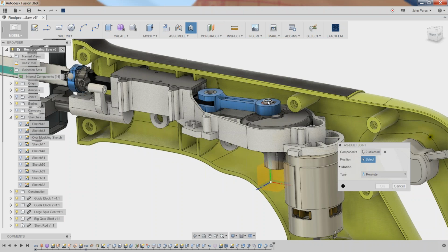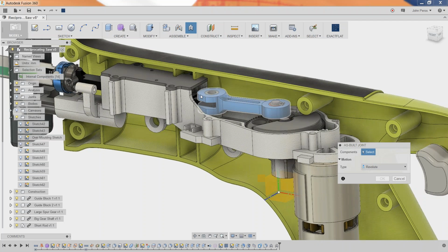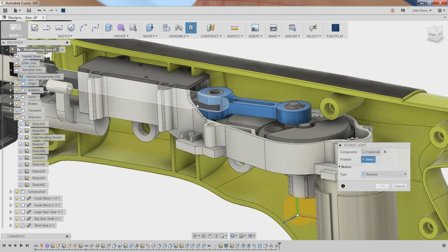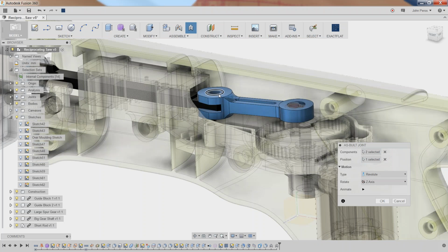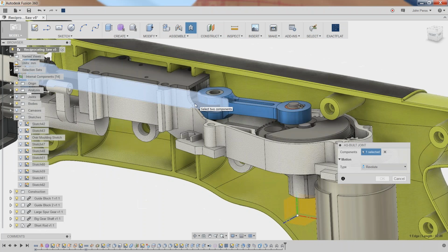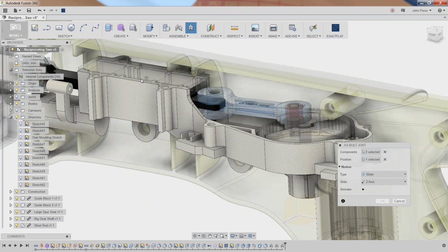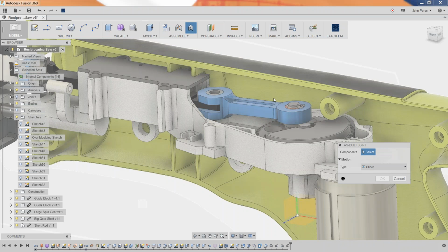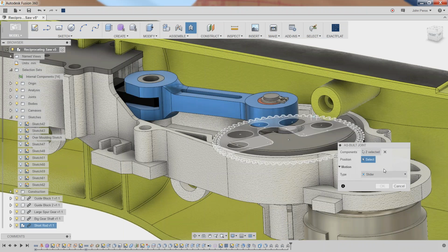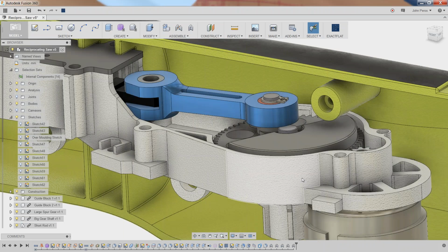And so we've got a couple other revolute relationships in here that we want to apply, but then I'm going to apply some other relationships as well. So the saw blade and the linkage have a revolute relationship, but the saw blade now has a sliding relationship based on this housing. So I can choose the slider and I can choose the edge direction, create that sliding relationship. If you wanted to create a rigid relationship, say between the clip and the pin here, you could set up a rigid and they're going to be fixed together just like that in that position.